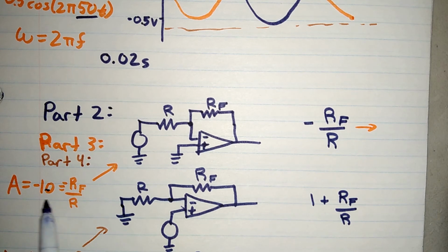If this is 10K, I can move this to the side. I have -10 times 10K, which is negative. Sorry, when you factor the negative, which will be 100K, because the two negatives will cancel out. So we need 100K over here for RF.